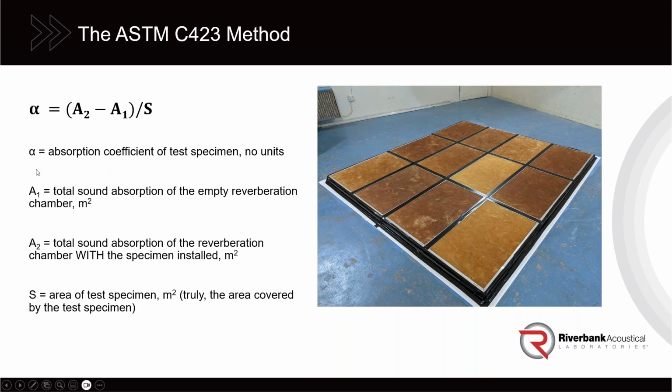Now, this term that is very commonly used in the science of acoustics, it's a little bit of a misnomer, and some people that come in from other areas of physics are sort of surprised that sound absorption coefficients can exceed 1.0. They can exceed 1.0, and they often do for highly sound absorbing materials.